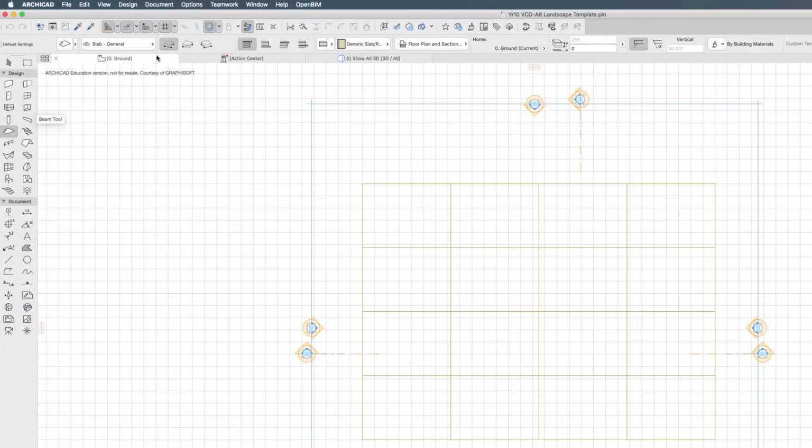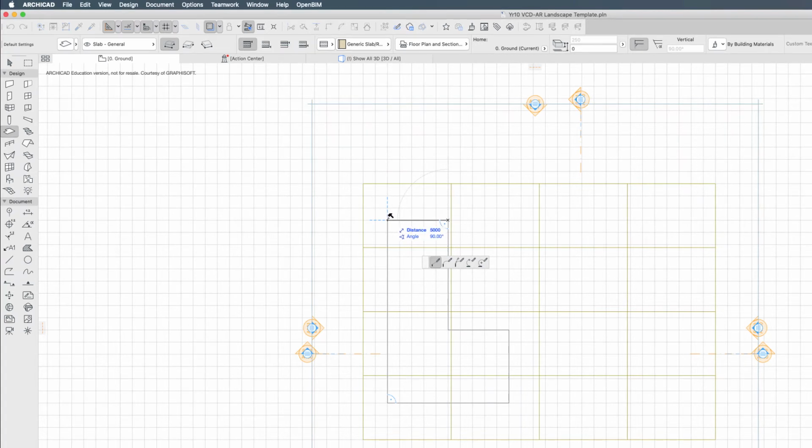So click on your slab tool, then choose how you want to apply your slab, either by line or using a rectangular method. Line by line allows you to create custom shapes, while the other option you'll have to do using rectangles. So line by line method looks like this. I'm going to start by creating an L-shaped house, just a small one, and I'm clicking on each of these points to lock them in, and then back to the beginning, and you'll see the icon will change, and click it to lock that in.